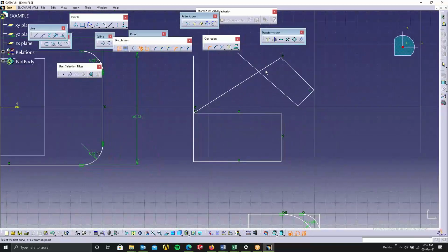Then here we have construction line trim. Whatever line is outside, we can make it a construction line like this. I didn't select it, sorry. Control Z. So we can make, yeah, standard line trim. Can select this construction line trim. So all the lines which are on the outside will become construction lines. If any constraints are in place, those constraints won't change.